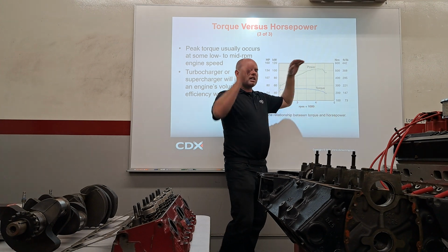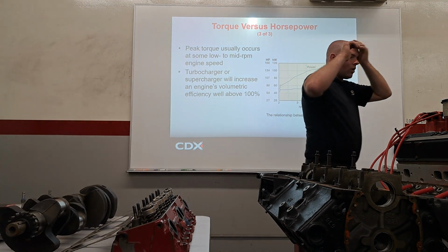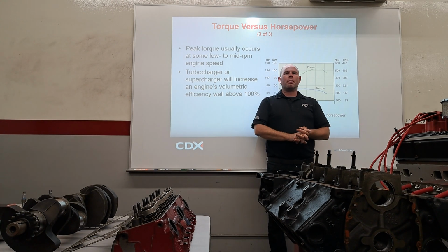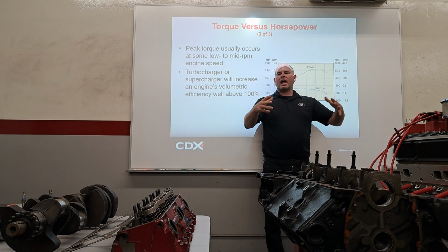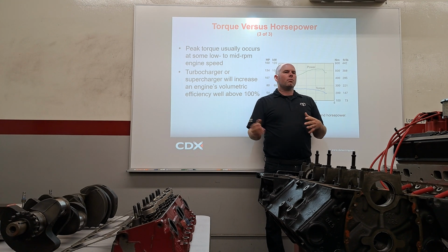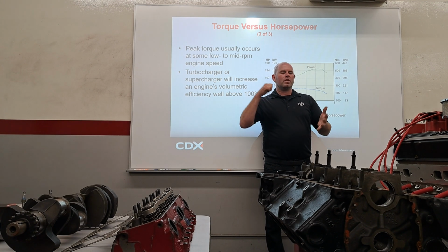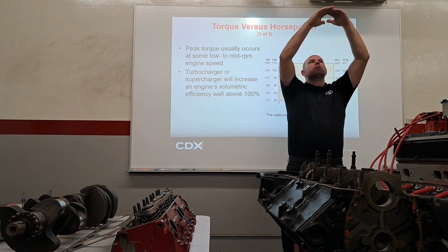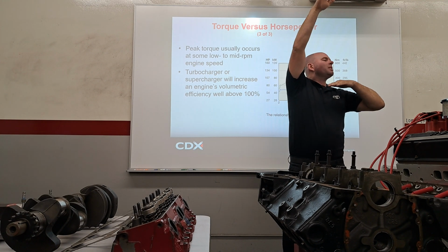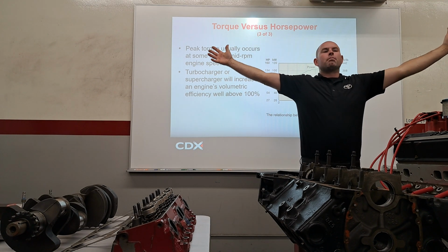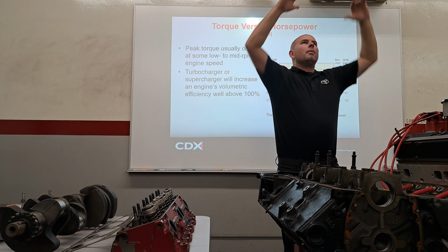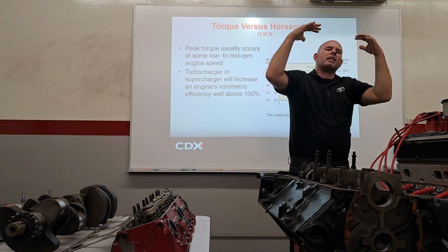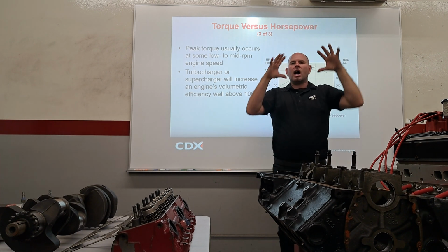And the reason for that is, if you think about this, right, we're gonna go way into detail. You got an engine, and you have to picture it as basically an air pump. The more air it can move, the more fuel you can add, the more power you can make. Cool? So let's say at low RPMs, you got your piston coming down and your intake valve opens up, right? So what's it doing? Kind of like breathing in. But it's not going that fast, so it can pretty much pack that intake stroke full, a lot of air.